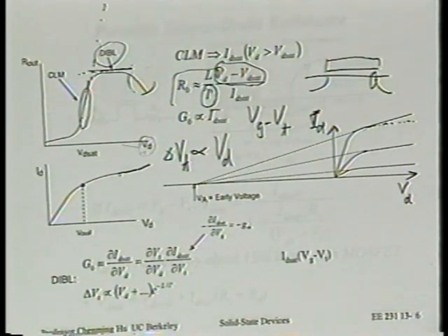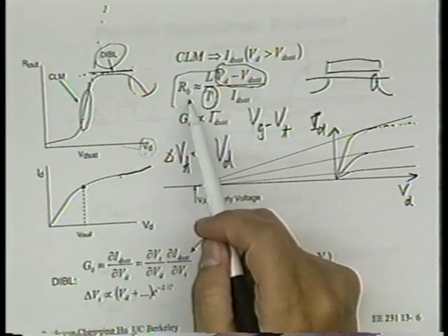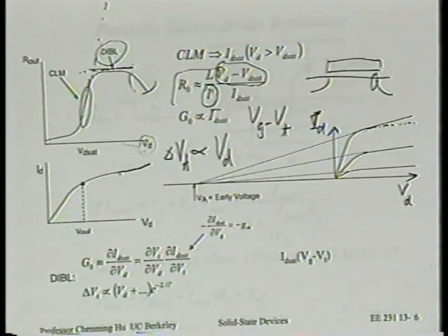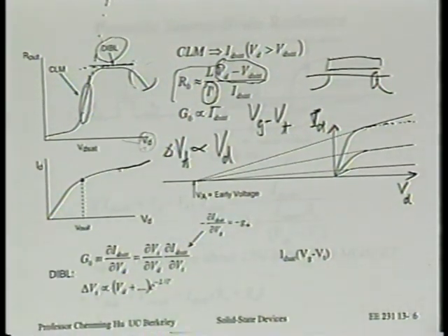All right. Let's start with you. Can you help me physically understand why, for channel length modulation, R naught is linearly related to Vd? Why would R naught be linearly proportional to Vd? I don't quite see that. It is, but is there an intuitive physical reason? Yeah, I don't have a physical reason for you. This is just taking the Taylor expansion of the first order term. That's the approximation made, right?